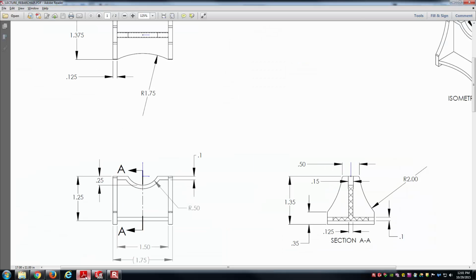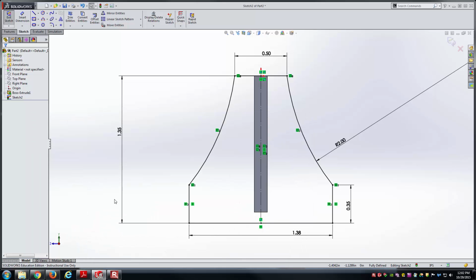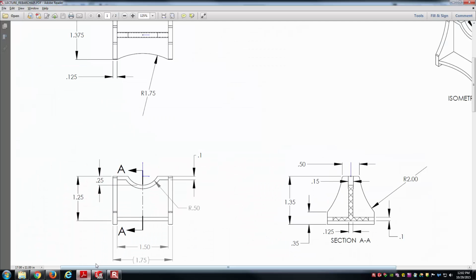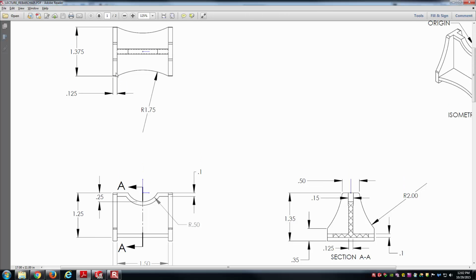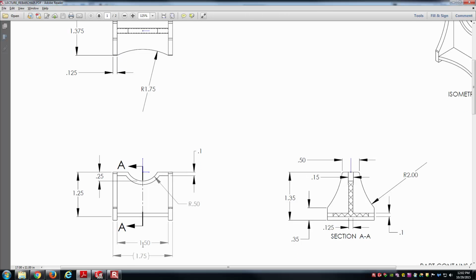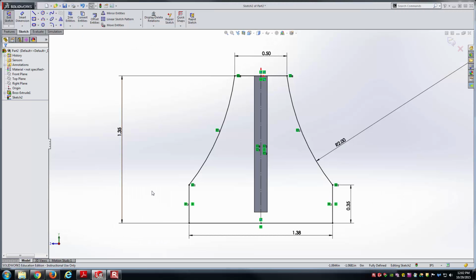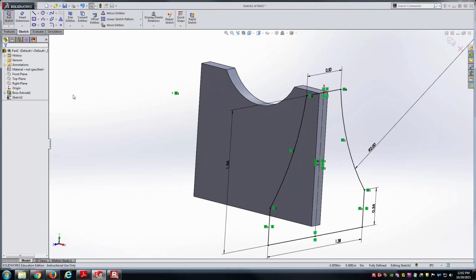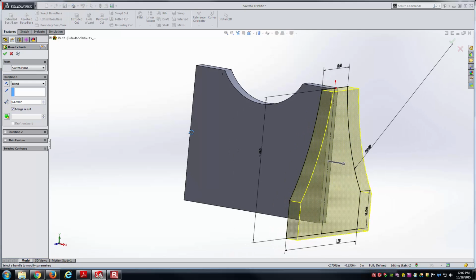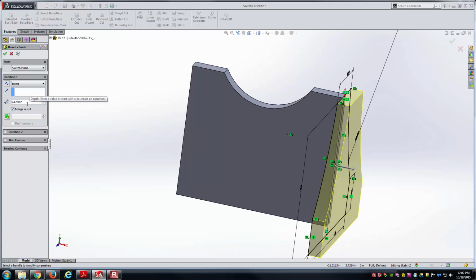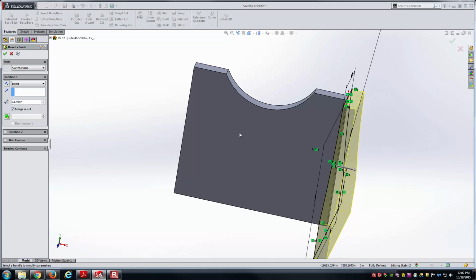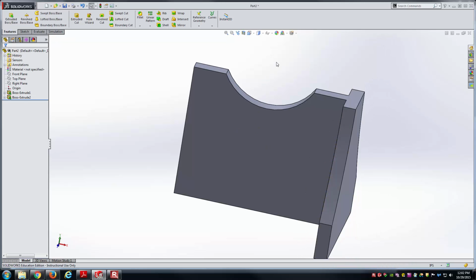So that makes it very convenient. So everything's looking good at this point. And so here I'm going to extrude it out toward the outside of the part. And you can see here they have 1/8 inch thicknesses on each side there to get to this overall width dimension of 1.75. And so my extrusion depth will be 0.125. So I've got here, it's already got the 0.125 from last time. It is going in the outward direction, so I can just go ahead and accept that.